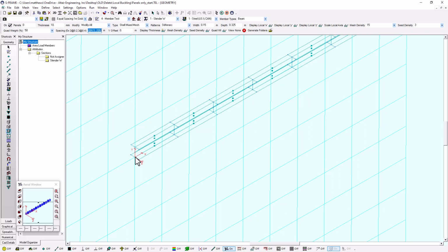My user coordinate system is going to act as my datum. So everything is going to be along the x-axis. I can say I want to have one stiffener at 0 meter spacing from the origin of my coordinate system in the x-axis. And then maybe I want to add another couple here. So I'll say I'm going to have 2 at 0.5 meter spacing beyond that. And then maybe another, I'll say 3 at 1 meter spacing. Once we've entered all this data, we can click OK to accept the changes, and then simply left click on my panel at the point that we want to place this.